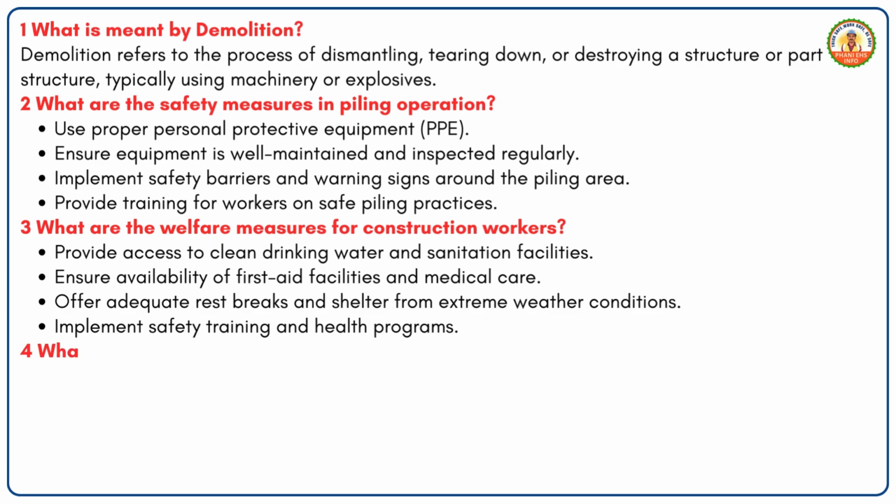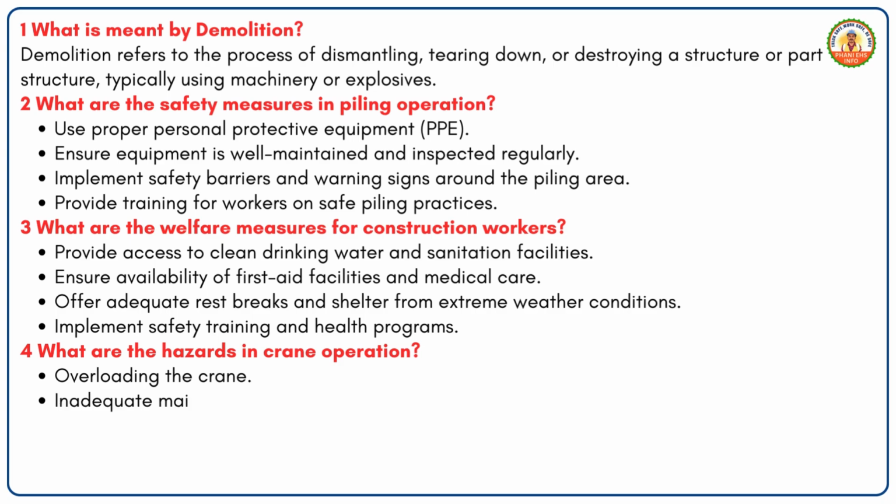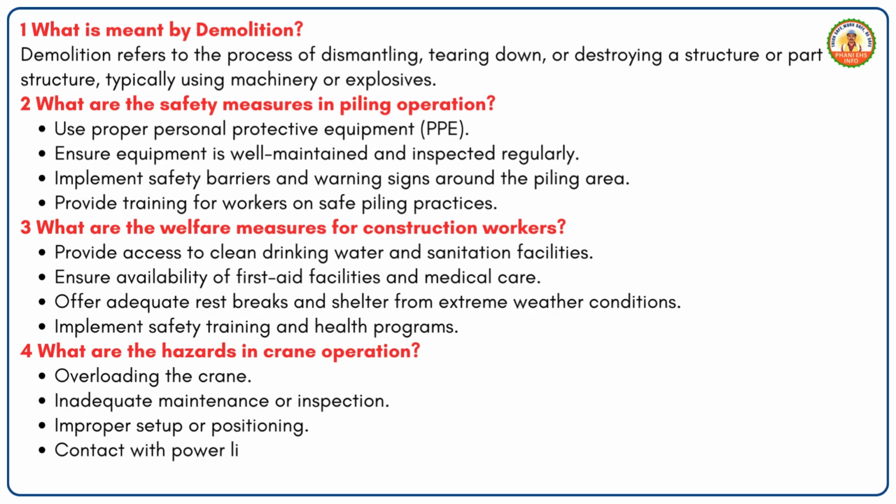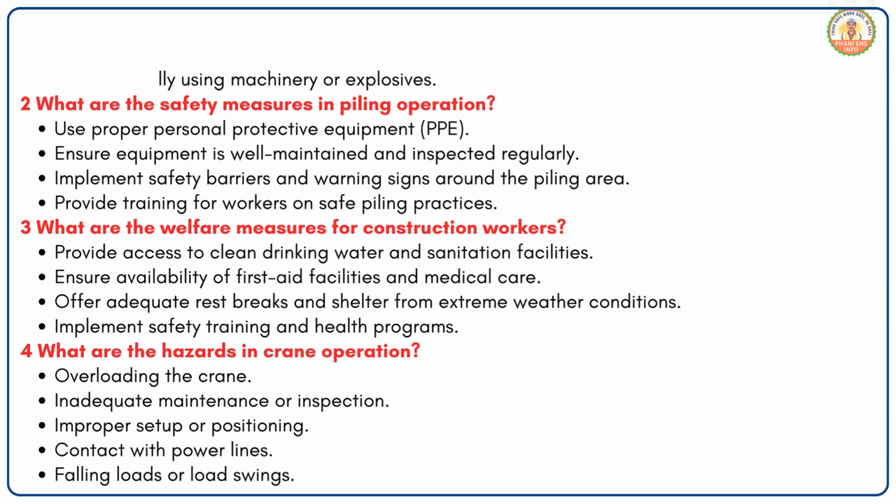4. What are the hazards in crane operation? Overloading the crane. Inadequate maintenance or inspection. Improper setup or positioning. Contact with power lines. Falling loads or load swings.